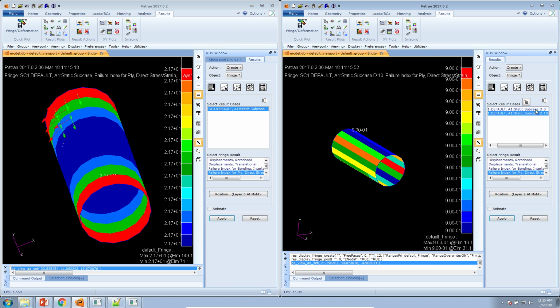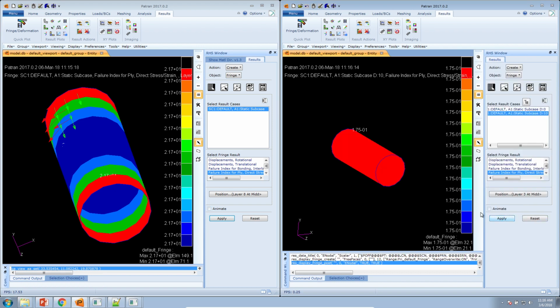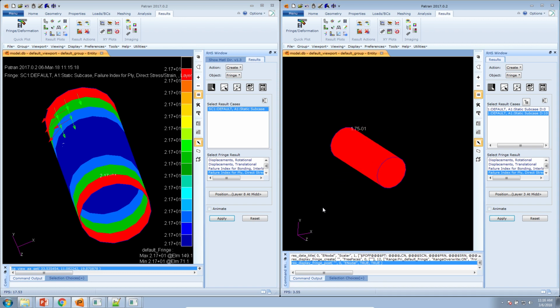The structural results are going to include results for the initial design, D0, and the optimized design, D10. The reason I encourage you to go through this process is just to make sure that all of your design constraints have in fact been satisfied.